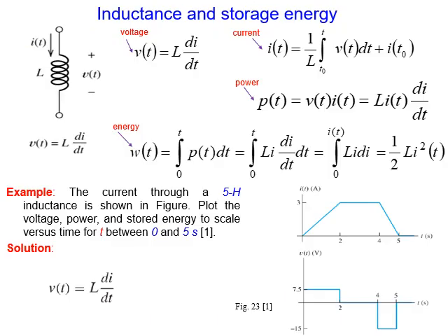And we can represent the voltage. By the way, just to remind you, for the capacitor the main player is the voltage. We have the voltage usually, so we find the current, which says current I equals C dV over dt. Now here in the inductance, it's the opposite. The main player is the current, so the voltage will be L di over dt.